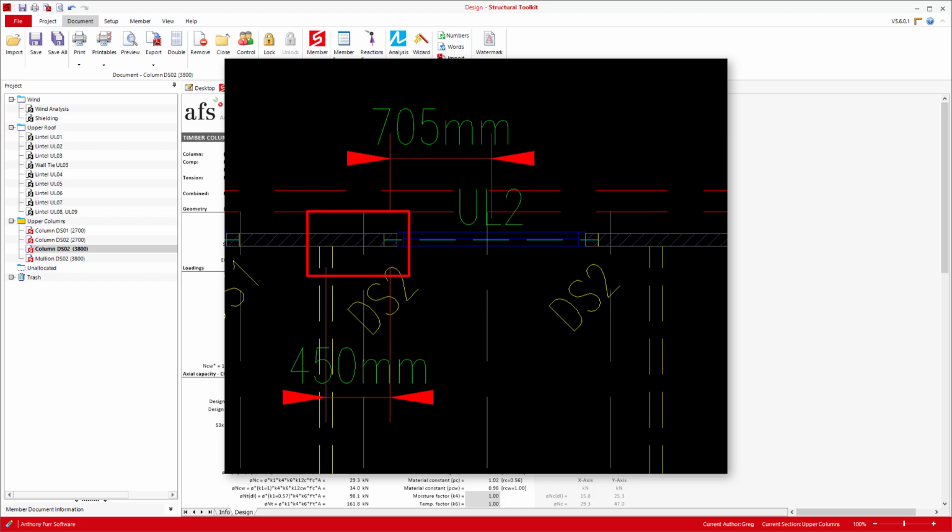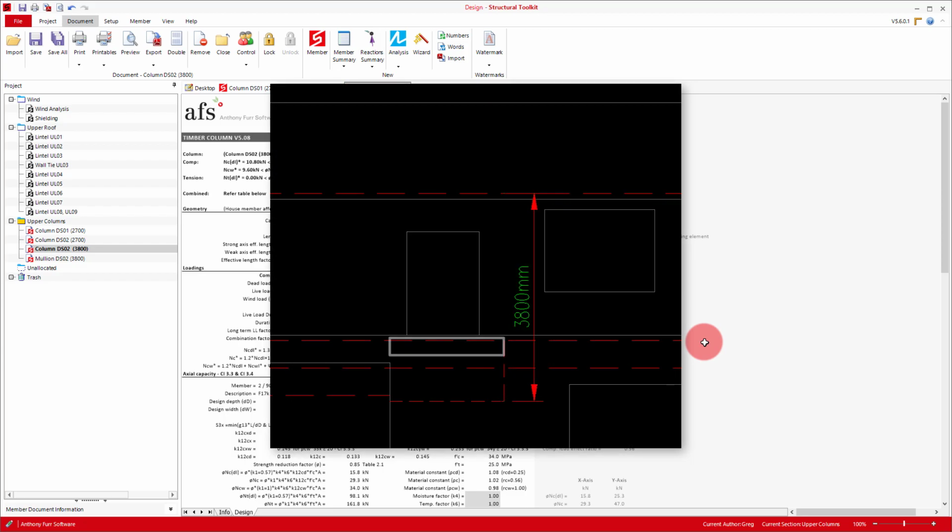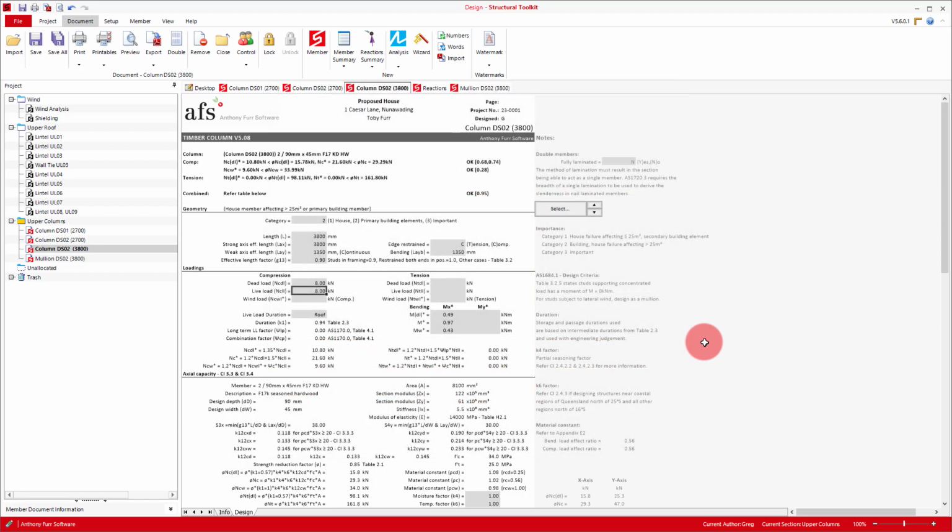If it were greater than 450, you might either design some studs using the mullion design or provide a wall tie between the return walls and columns, so that you can still use standard framing in between. Or you could even design a wall tie that spans the entire void, meaning you won't need to design the mullions that we did.